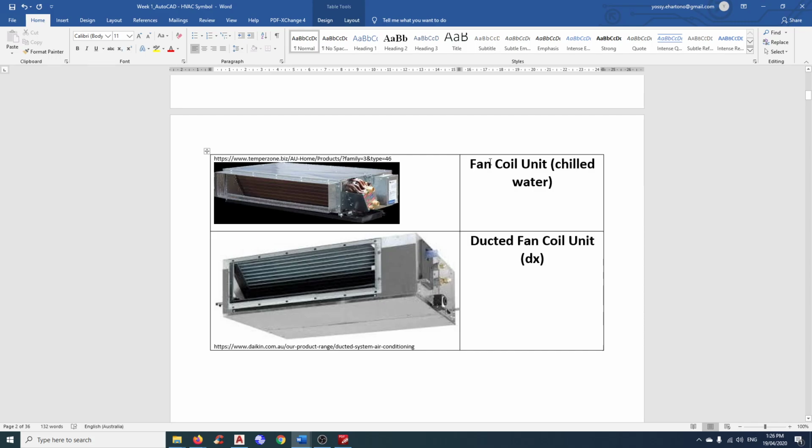We're just going to say an air handling unit is more like a bigger box, while the fan coil unit looks like this, where everything inside is compactly made and proprietary from the manufacturer, while an air handling unit is built on request because you can resize it as much as you like.